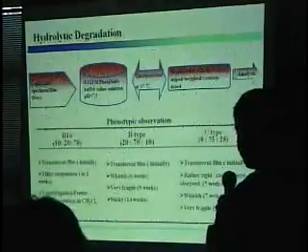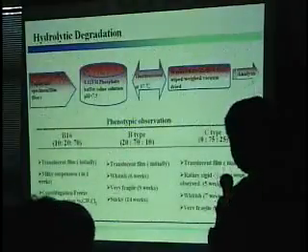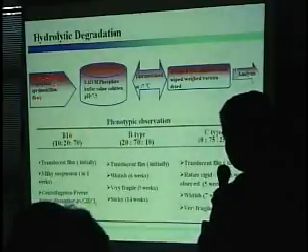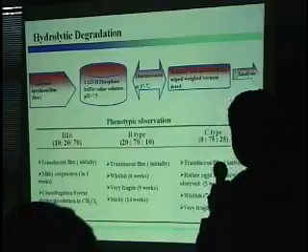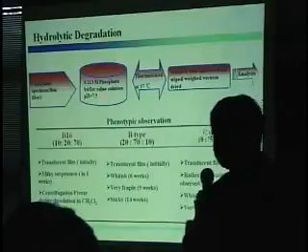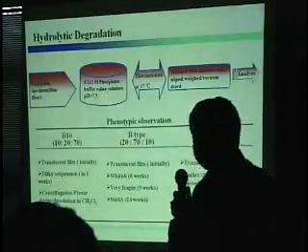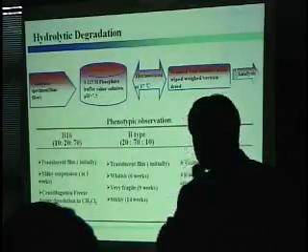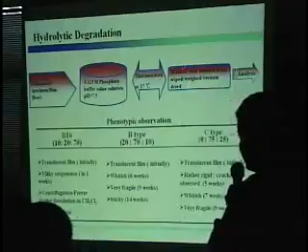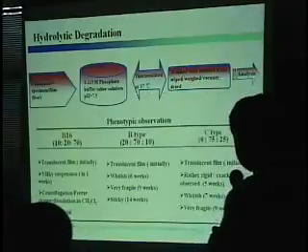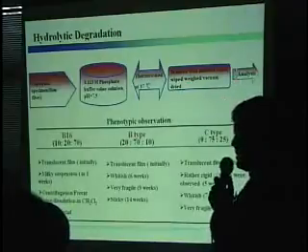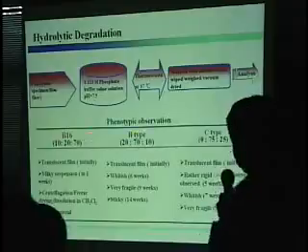Next slide, please. This electrospun membrane was furthermore applied for hydrolytic degradation, and both the film and the fiber membrane were used. This is the phosphate buffer solution, with a pH of 7.5. The samples were subjected to degradation at 37 degrees centigrade, and at different time intervals, they were washed with distilled water, vacuum dried, and at last analyzed. These are some results, the phenotypic observation.